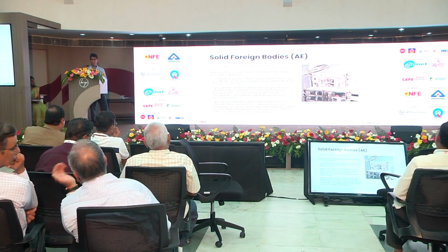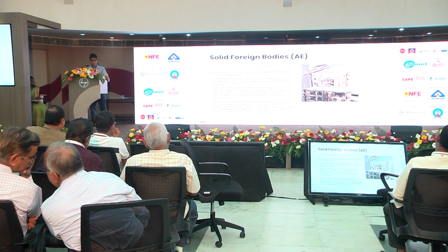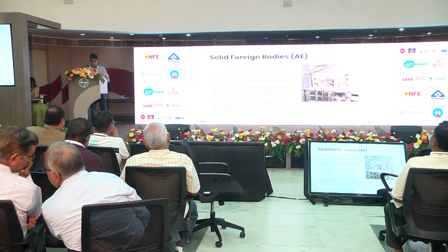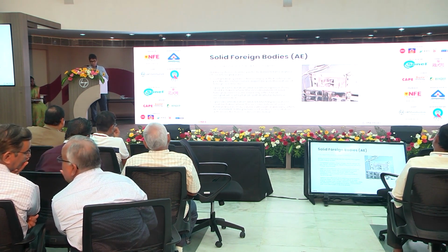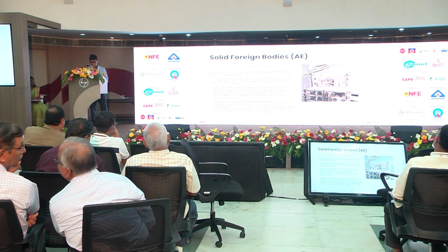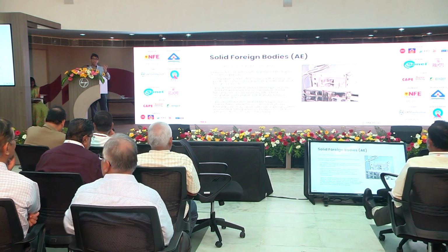So as you know, when you have IP ratings, you have two numbers. The first number is protection for solid foreign bodies. The second number is for water ingress. So you can look at 60529 for this. So again, special considerations must be taken. Again, if the dust is going to accumulate, this is going to then limit heat dissipation.